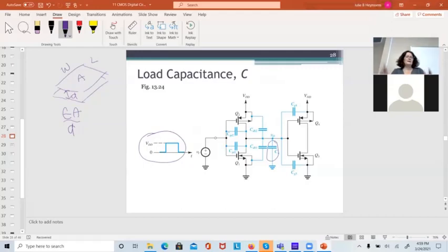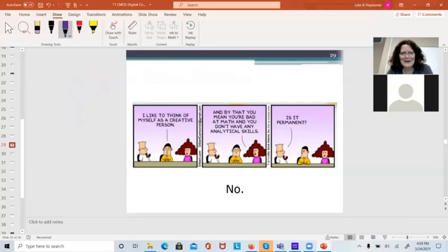So if I can make the area of the transistor smaller, I can make the capacitance smaller, and I can run them faster. So that's one place where I can pick up a freebie by using the multi-billion-dollar process to make things smaller.